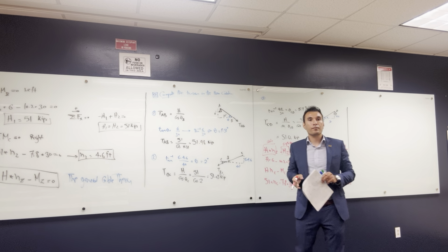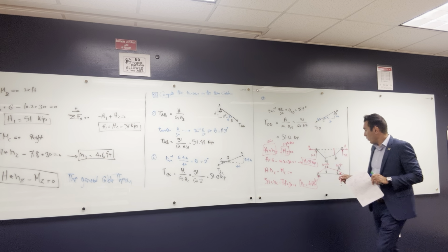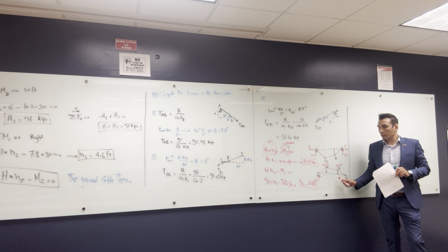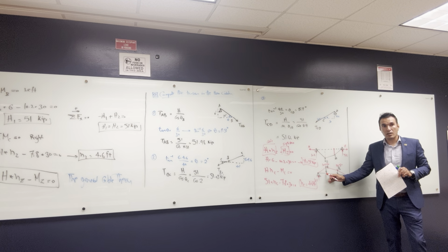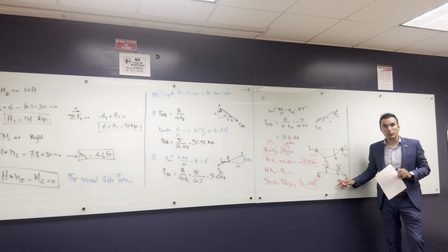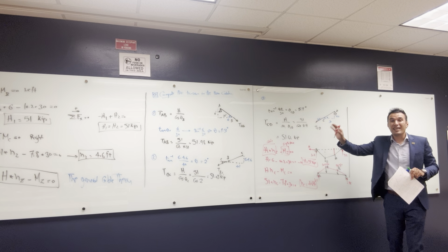Okay? The moment is taken from which point? The moment is taken from the equivalent beam, and Mz is at that point. It is the bending moment from the bending moment diagram of the equivalent beam. You draw an equivalent beam, you put the same load and deal with it as a simple beam. Once you deal with it as a simple beam, draw the bending moment diagram, take this moment and put it here. It is the same thing.